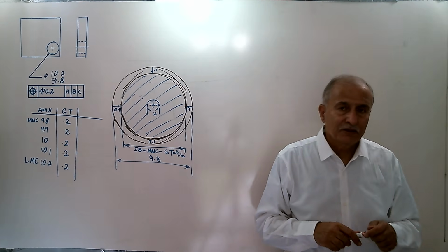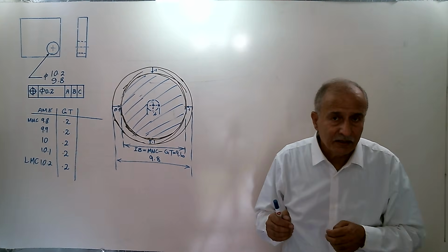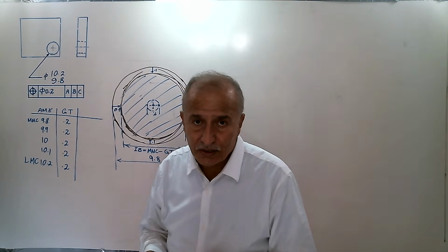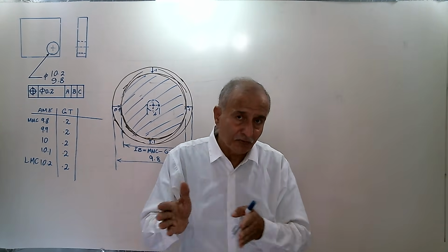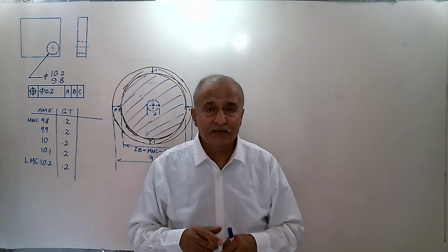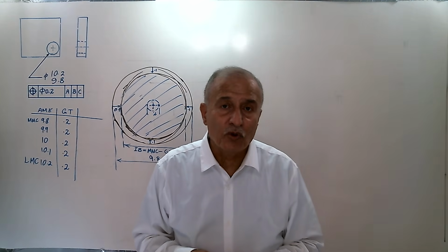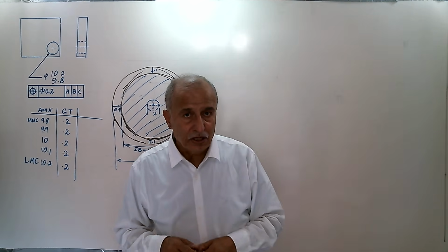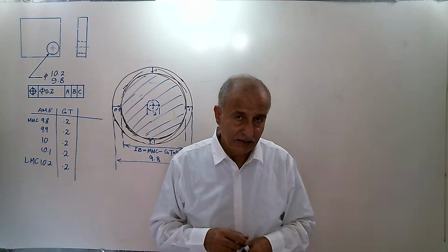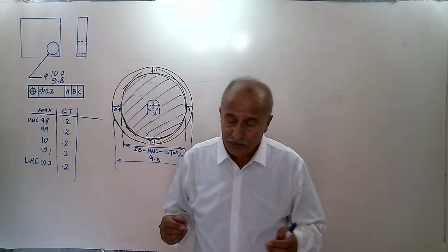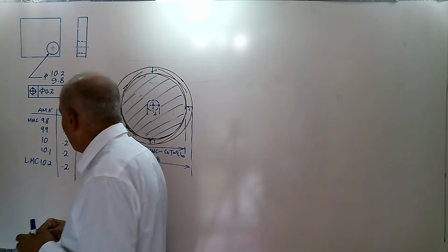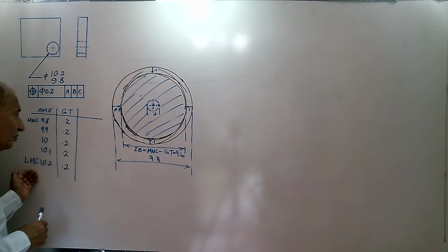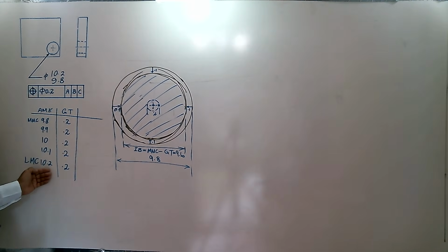The hole can be made at 9.8, but with error, any defects inside the hole or with the axis that displaces will be smaller for us if the goal is assembly. But RFS doesn't tell anything about assembly. What happens if we produce the hole at 10.2?